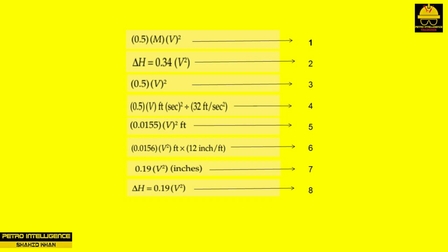Nozzle exit loss calculation. My standard calculation for nozzle exit loss, as shown at the start of this video, is delta H equals 0.34 V squared, where V equals velocity in feet per second, and delta H equals head converted to velocity, in inches, measured from the center of the nozzle. The coefficient of 0.34 is one that I've arrived at by measurement in my water barrel and bathtub, and then added a small safety factor for design purposes.